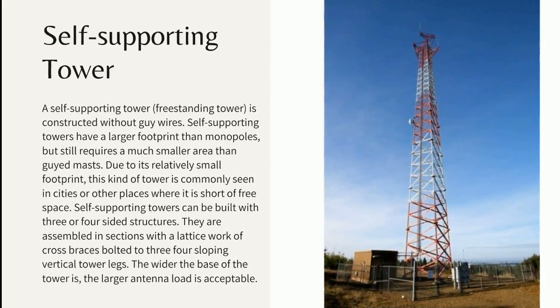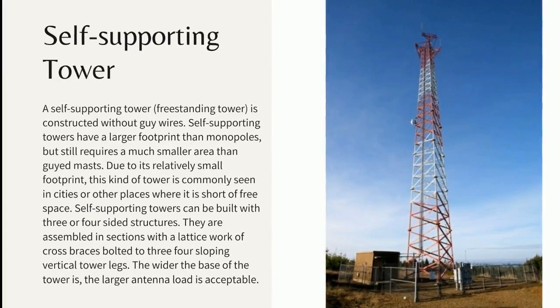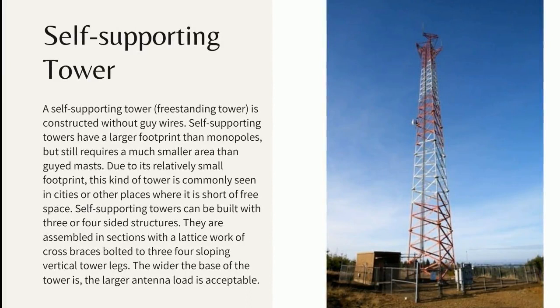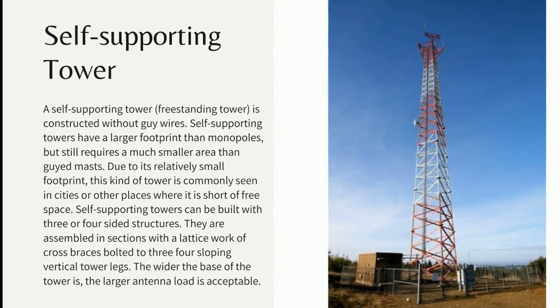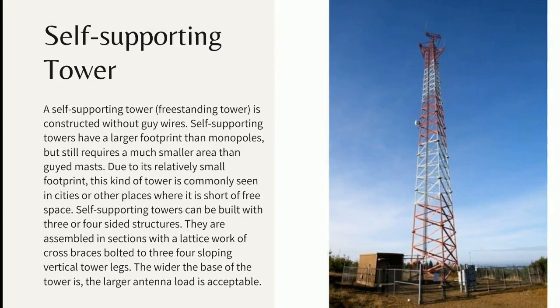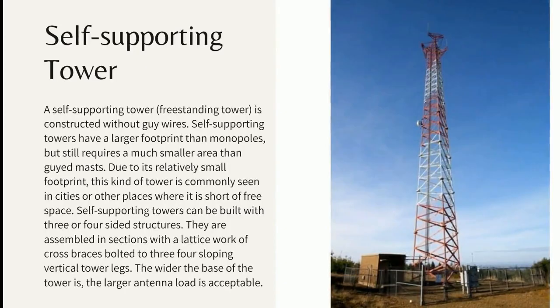This tower can be built with three or four-sided structures. They are assembled in sections with a latticework of cross braces bolted to four sloping vertical tower legs. The wider the base of the tower is, the larger antenna load it is capable of.